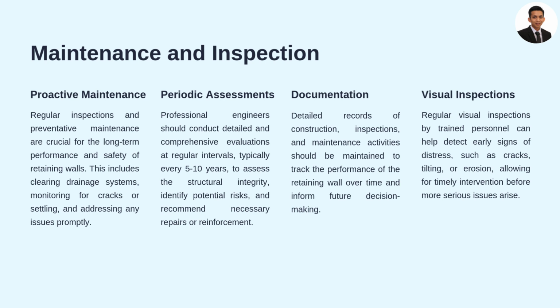Maintenance practices. Repair cracks using epoxy injection or grouting techniques. Replace corroded reinforcements or anchors in anchored walls. Clean and repair drainage systems regularly to prevent water accumulation.